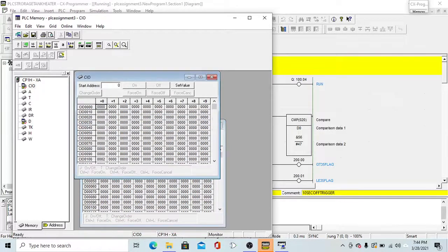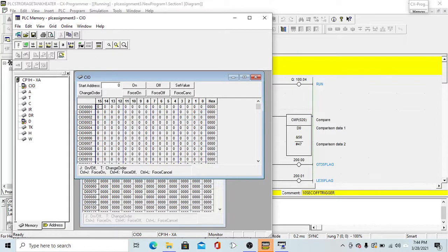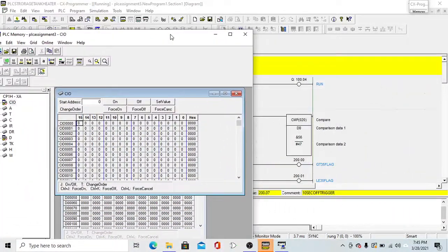The first thing you need to do before you even attempt to manipulate the memory locations, you have to go to the tool here, so that changes the display into being binary. That way you can actually change the bit for each register. Each of these columns are registers. So if you notice, the start is located at 000.0, so we're going to change that to a 1. Just double click and click OK.